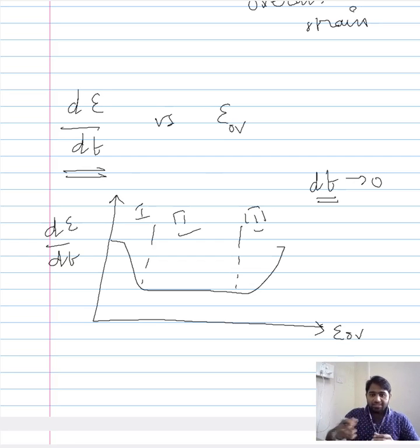So by considering the overall strain on the x-axis, we arrive at this creep strain rate plot directly by looking into the behavior of the material. Now if you consider t here and epsilon, the strain, here, you would have your conventional creep curve, and we saw that the way of arriving at the strain rate curve is by considering its slope.